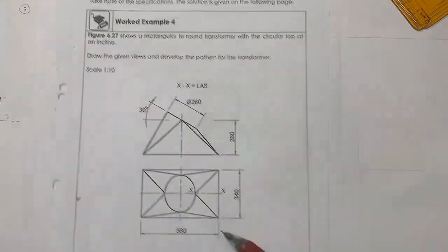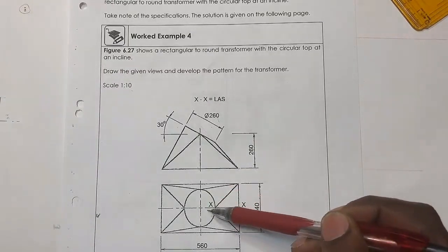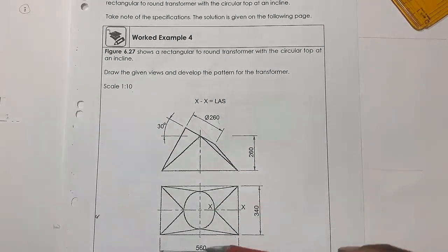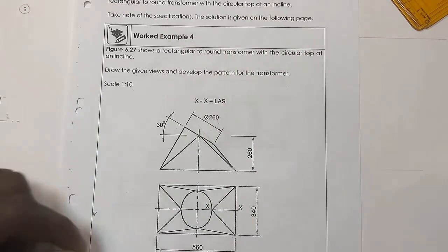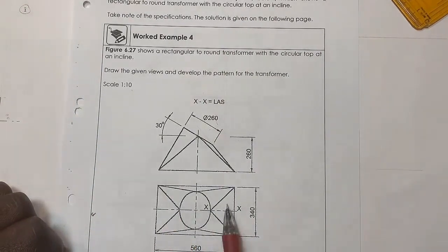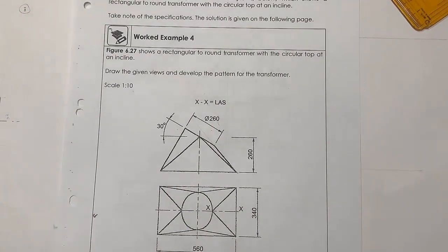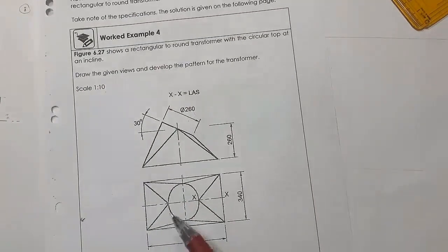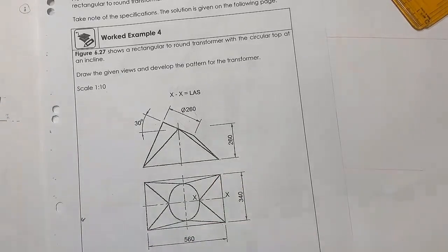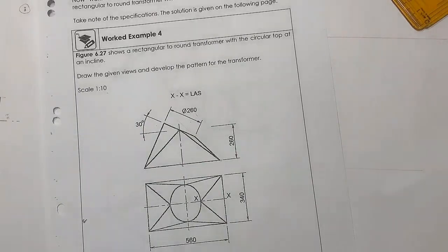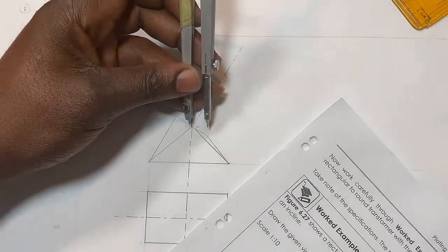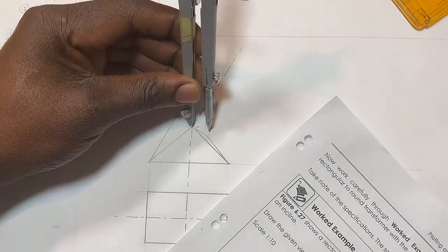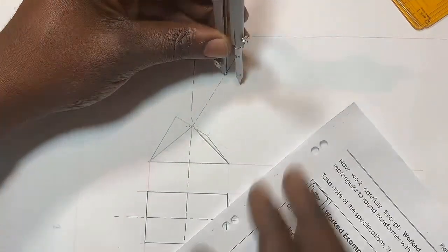So then to draw the top view, this one is not going to be an exact circle, because this is your top, right? When you view this part on your top view vertically going down, it's not going to be just a round circle as normal, such that you can easily draw it with the drawing compass. It's not. As you can see, it's a little bit of an ellipse. You understand? So to get that, you have to construct points. You understand? So what I'm gonna do now, I'll draw a what? Auxiliary view just a little bit away from my front view.